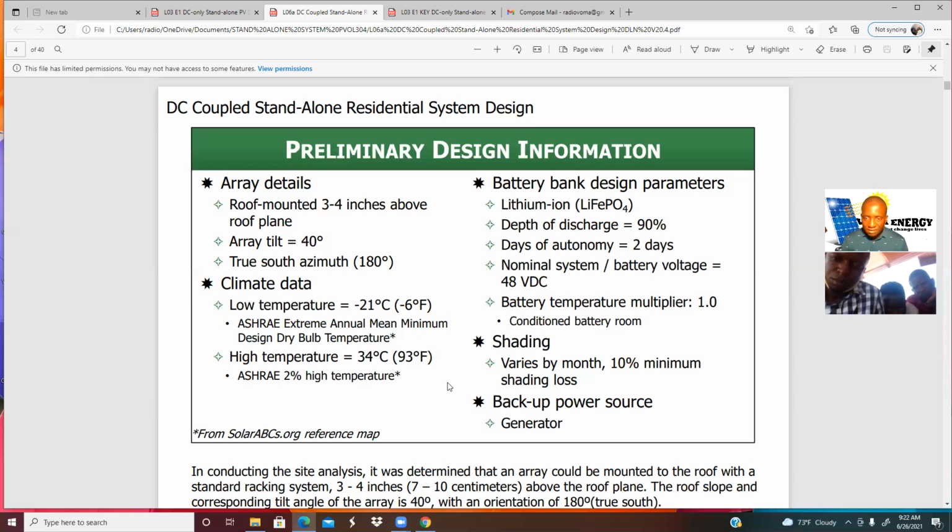The nominal system voltage, the battery voltage, equals 48 volts. This is very important. The system voltage, when we went to design the system at Bobby's house, Mrs. Whitehouse's shop, you had a problem with using a 12 volt inverter on the system. Do you guys remember that the inverter would not even light on? Because the system was a 24 volt system.